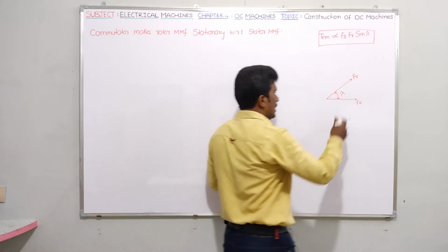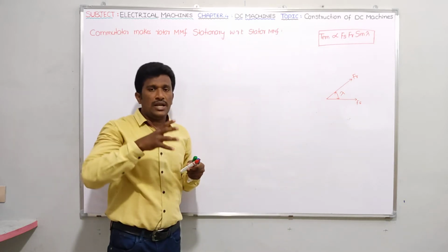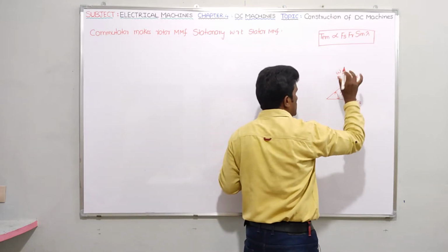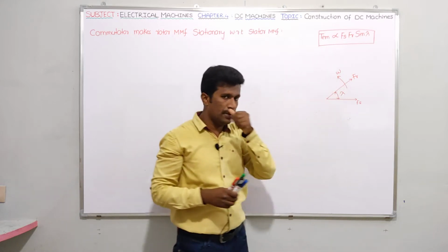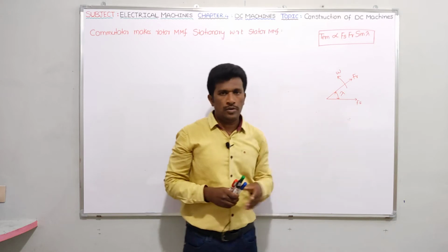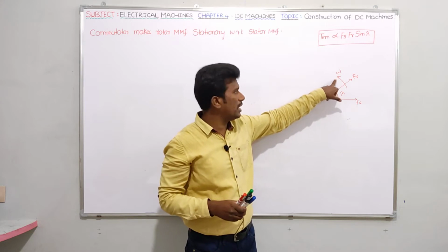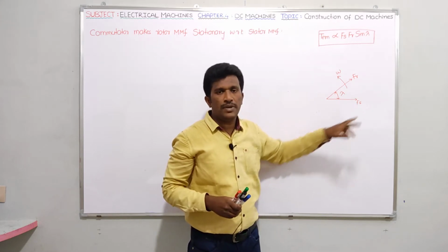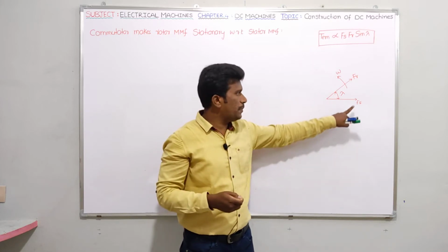Right guys, here the problem is, for example, let us assume a DC machine, in which we place the armature winding on the rotor. Rotor is the rotating part. For example, if the rotor is rotating with omega speed, omega radians per second, in the anti-clockwise direction, the problem is, I told you the relative speed between 2 mmfs should be equal to 0. Now you already know that in DC machine we place the field winding on the stator. Stator is a stationary part. So what is the speed of stator mmf?